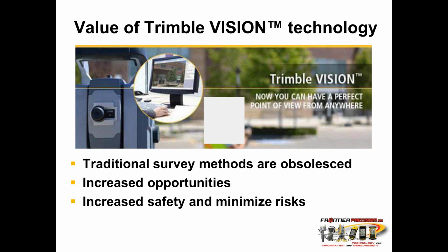The one application that I'd like to discuss, and it shows a great example, is that because everything that's seen through the camera on Trimble Vision can be seen on the data collector, we were working with the military on three total stations set up to be able to trilaterate or triangulate on the ordnance where they're landing, and that required 3 personnel out in harm's way. By the use of using Trimble Vision technology, we were able to become creative and mount 3 total stations,